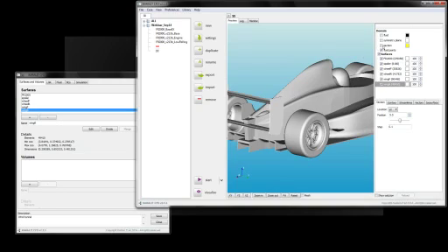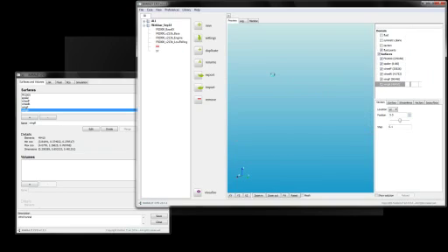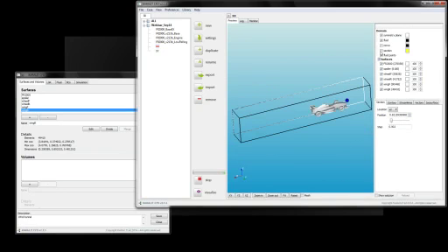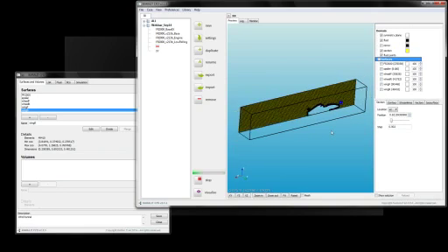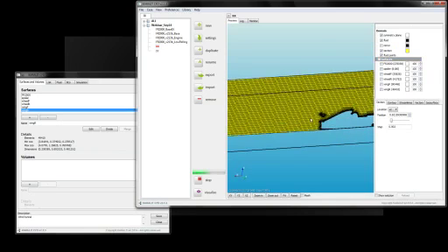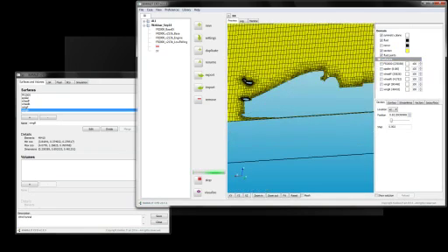It's a Cartesian mesh, but in an immersed boundary framework. So if I show you the mesh on this case that we are running, you're essentially taking advantage of immersed boundary and applying the boundary conditions of the surface at exactly the right positions, but you're not actually generating a body-fitted mesh, which is very time-consuming.